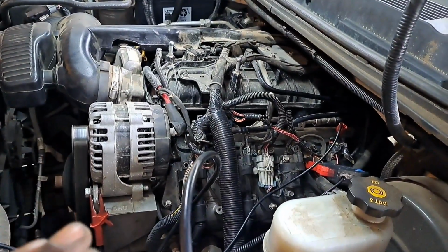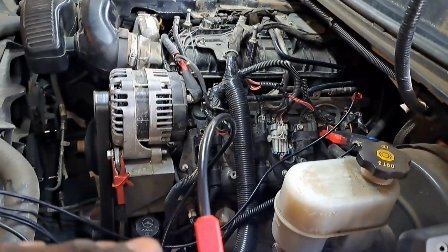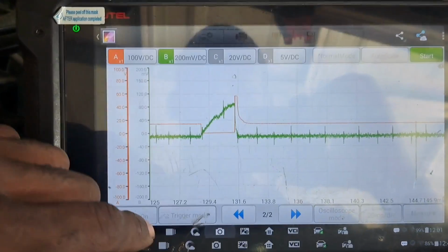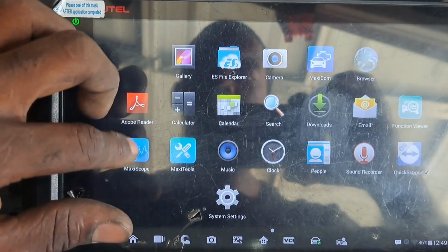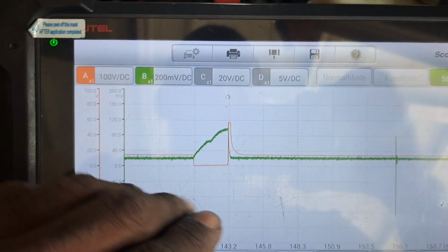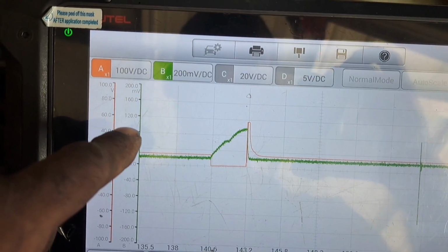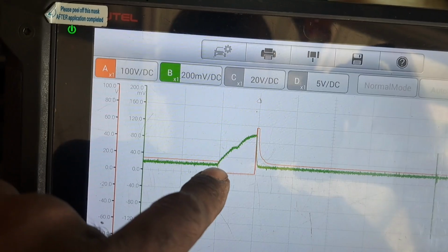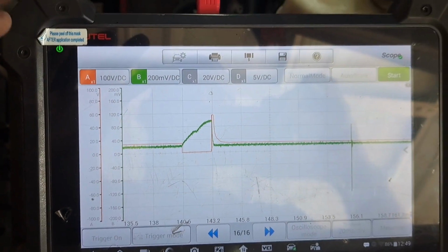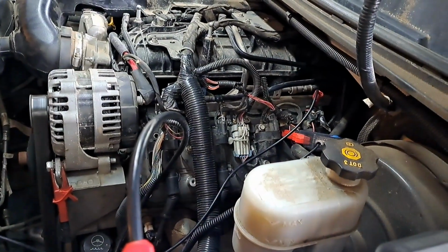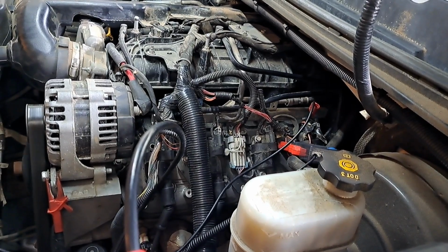So pretty much, I tested all the injectors. The waveform came out fine. They were all uniform. And I was on number 7, that is not where I need to be. I questioned number 7 and number 1, but they all were uniform, made below 60 volts, and current ramp was right at 1 amp. So I'm not gonna question it so much. The only thing I can do is pretty much replace those injectors or swap them if I want to be absolutely safe.